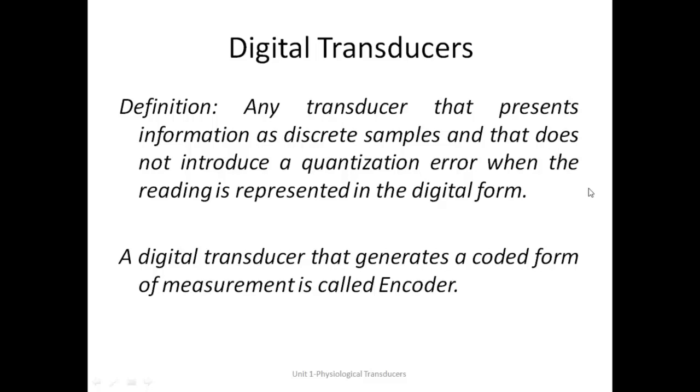The type of sensors that we have been using are all analog in nature. Suppose a piezoelectric crystal, it is giving you an output in terms of voltage. Now voltage is an analog quantity, it is continuous in terms of time and magnitude, whereas the digital displays that you have are discrete in nature. That means you need to convert this analog output into some digital form, some discrete form, which can be displayed in terms of some numbers, which can actually be understood easily by a layman or by the end user.